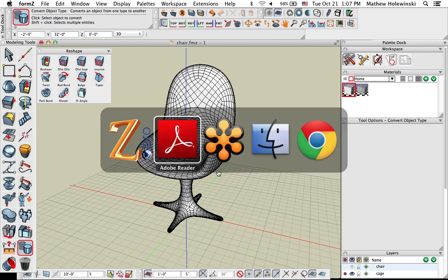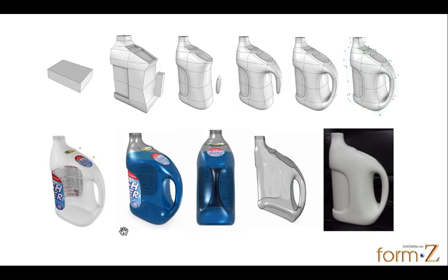Let's look at some other examples. If we go back to our slideshow here, let's do something a little more complex. So that chair is pretty easy, and the bottle gets a little more detail into that. This is a neat way that we can take a subdivision object and convert it into a NURBS object, and then continue to edit additional features into it as an actual NURBS object. And of course, we can add rendering effects, and we can do some cut type cross sections. We can thicken it to give it the actual thickness, and then get it ready for the 3D printing process. So this one will be a little bit different, because instead of a subd object being converted into a quad mesh, we have a smooth NURBS object that we'll have to convert into a faceted object for the 3D printing. So we'll look at some different ways that we can do that.